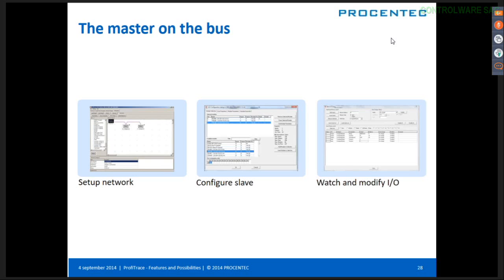Okay, you're back again. There was a short question. So with Profi-Captain, we can test and set up our device, we can see if the temperature is sent over the Profibus. We can change the device address. For example, if you have PA devices, there's always a software-set address in this device, and we can change it very easily with Profi-Captain on our desk. We can see all kinds of data going on. We can set up outputs. We can change everything. It's just a test or evaluation master.